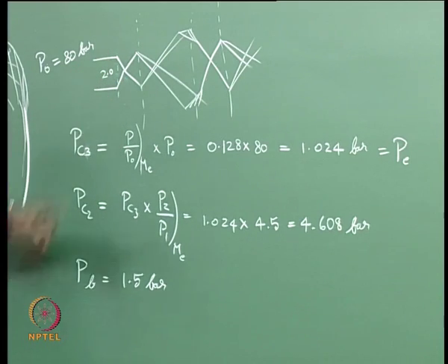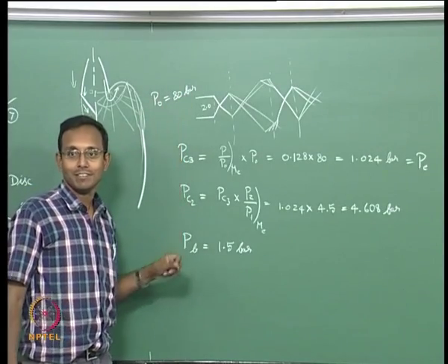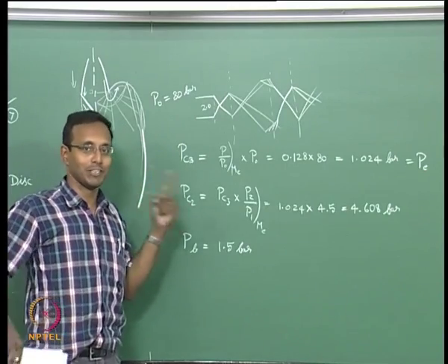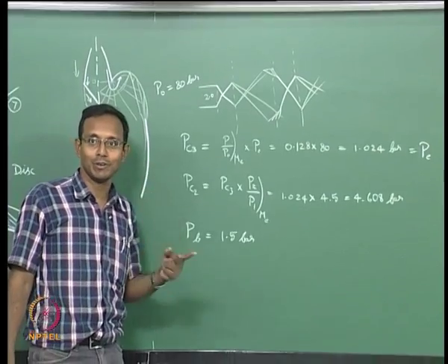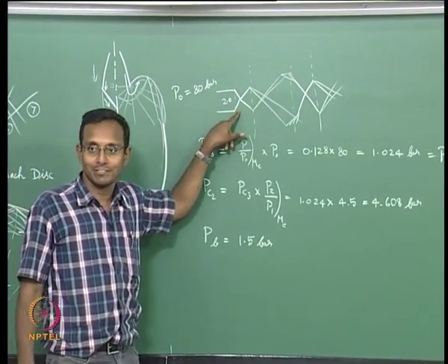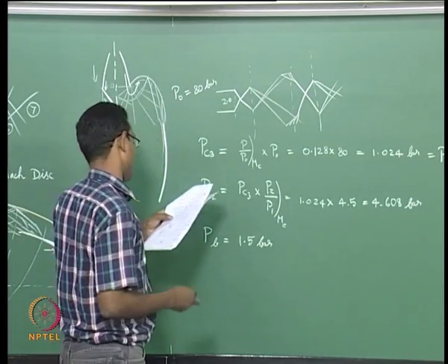That is the job of this shock. Previously we used to do this flow angle turning as the boundary condition. That is a simple thing. I told you gas dynamics has two things. One boundary condition is pressure, other boundary condition is flow velocity vector direction. In this case it is not velocity vector direction, it is the pressure. So I want to match the pressure.